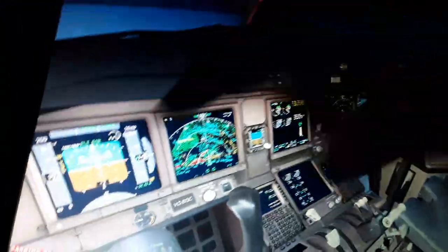So I told you about the primary flight display. You can see the airspeed displayed, and I'm going to start with the primary flight display of the Boeing 777-300ER. It displays the minimum airspeed, the indicated airspeed, the ground speed, the airspeed selected from the autopilot and flight director system panel, the barometric altitude above sea level, the barometric pressure of the outside atmosphere, also the rate of climb and descent, and the target altitude we set from the autopilot and flight director system panel.